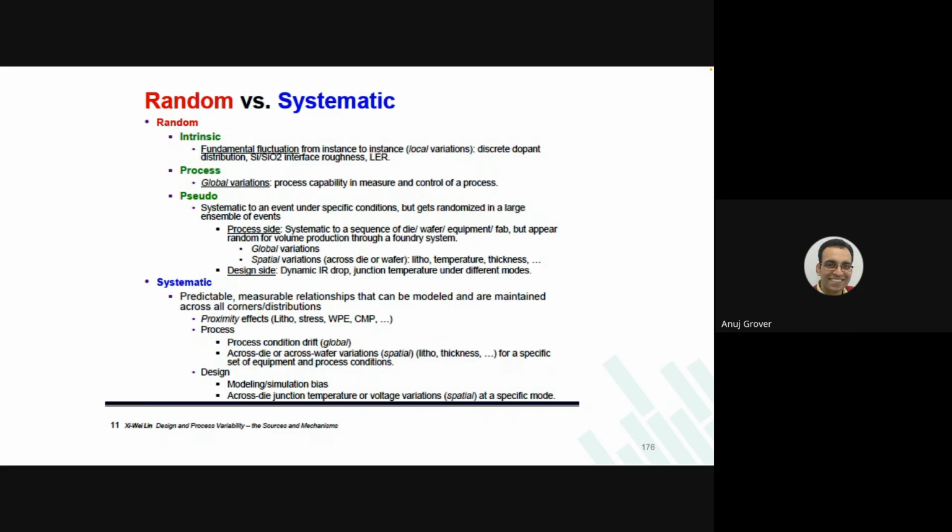So if we consider something like coupling, would that also be event dependent? Like if you have that event, only then the coupling will happen, because it might not. Yeah, we looked at the impact of Miller capacitance, Miller coupling. So yes, that you can model based on events.